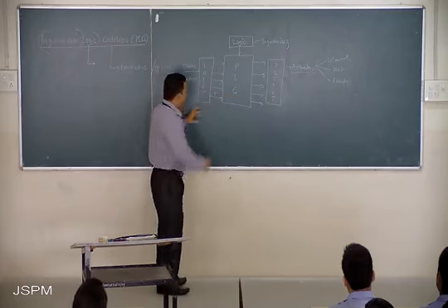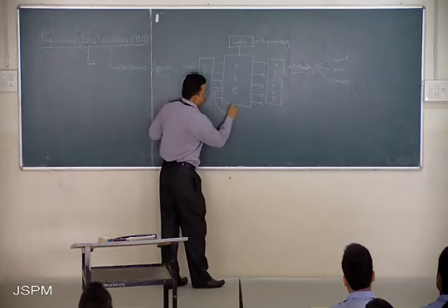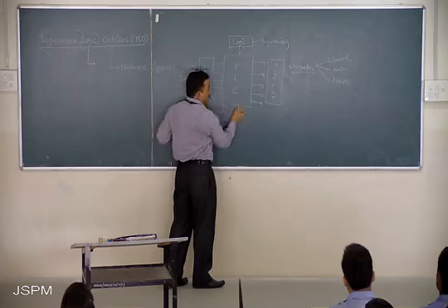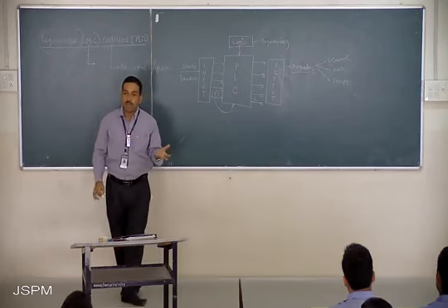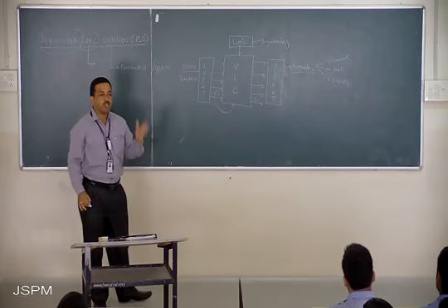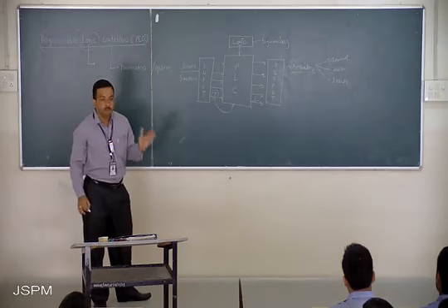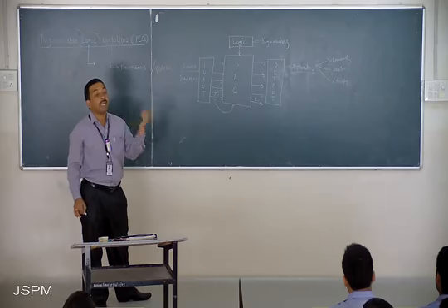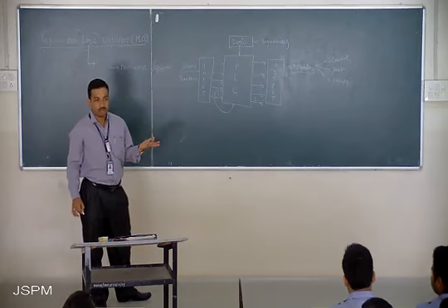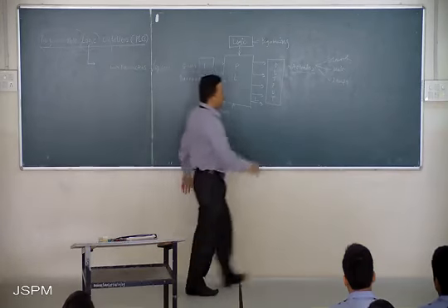Based upon the temperature value, the PLC will process it based upon the logic, and the output will occur, that is, it will glow the lamp. If the temperature is within the limit, a green lamp will be on. If the temperature is crossing a particular safe limit, the red lamp will become on. Are you getting me? Okay, and we have alarms.